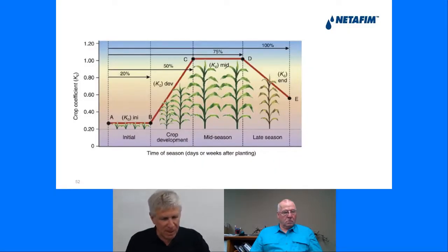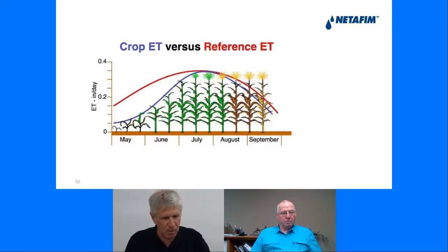The other item that we need to define is the crop coefficient. We get the KC according to the phenological stage of each crop; in the beginning, the KC or crop coefficient will be very low. Normally, when we design the hydraulic system, we look at the peak demand, when the crop is using a lot of water on a daily basis. We measure the ETo, which can be either from a pan or from an equation, the Penman-Monteith equation. We multiply the ETo that we get from the climate data by the KC of the crop, and we actually get the real crop consumption.